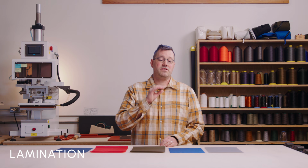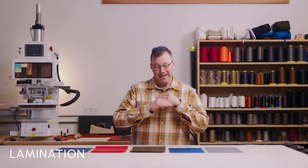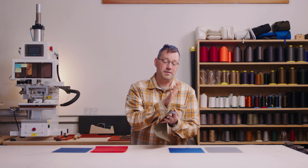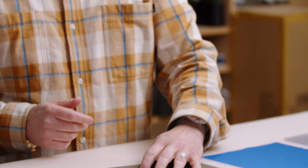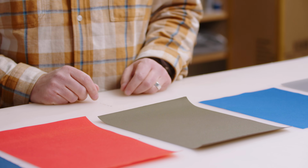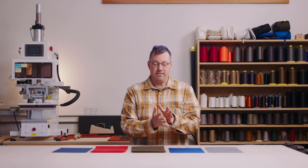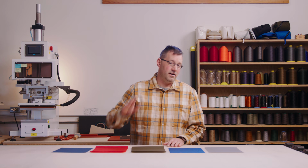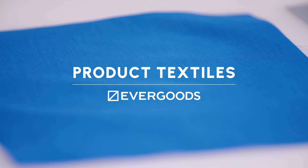A lamination starts as a single layer, like a film almost, that is a solid film, and it is applied and bonded to the back of a textile. So that is lamination. Finally, we can talk about composites. Composites are just multiple layers of textile or other materials that are all bonded together into a sandwich to make a thing that is the combination of all these elements.